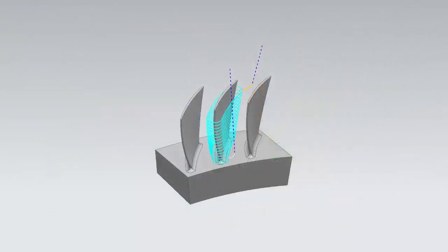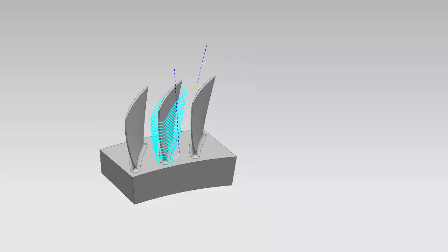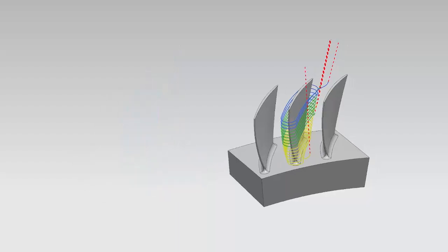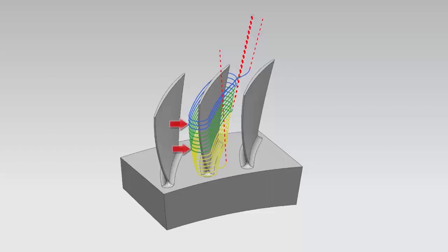To maintain stability of the blade when finishing, it's common to rough all instances to a certain depth, exposing the upper stripe of the blades, and semi-finishing and finishing that stripe before roughing to the next depth. While this process was supported previously, the finished blades showed marks between the stripes.